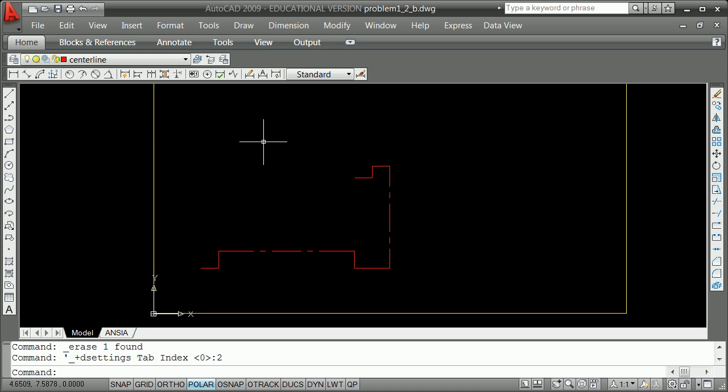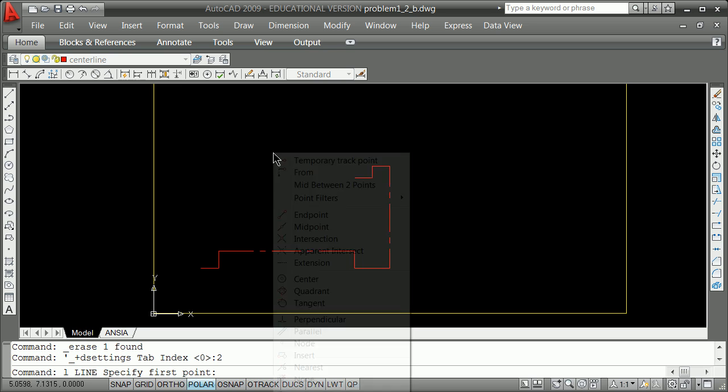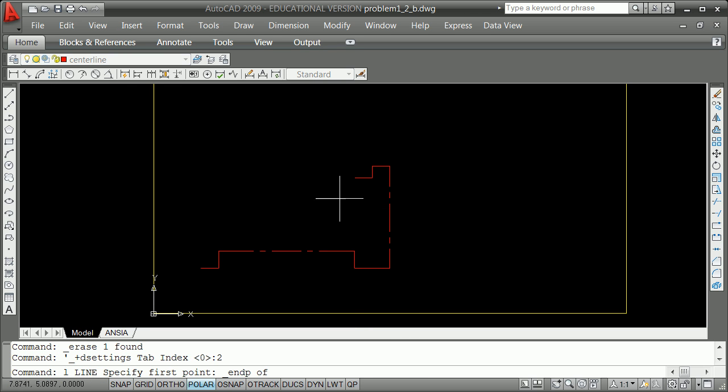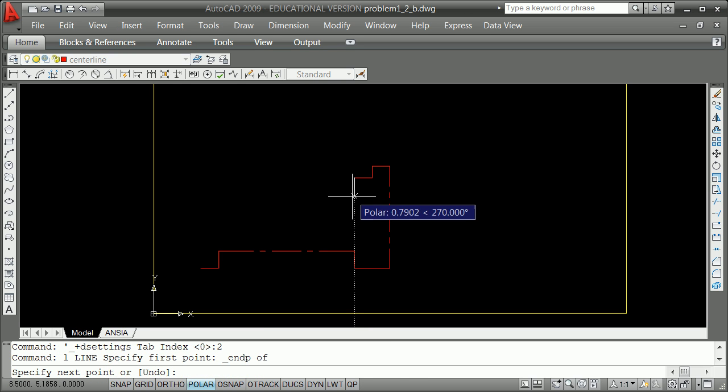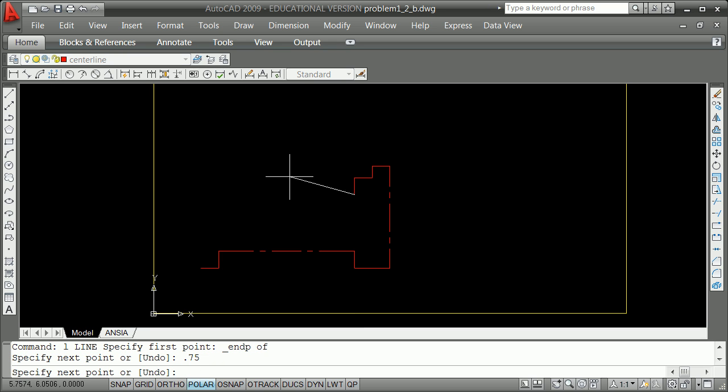So once again, L for line, Shift right click once you have something on the page. The most correct thing is to actually use the Shift right click. It is not to type in the coordinates. Even if you wanted to go back to 0, 0, that's not the thing to do. So we're going to go down now, thinking about it, 3.25, we wanted to go down 0.75, and now there's little chance of us, because we have the lock on the way it is, if we have our hand off the mouse, this is 1.